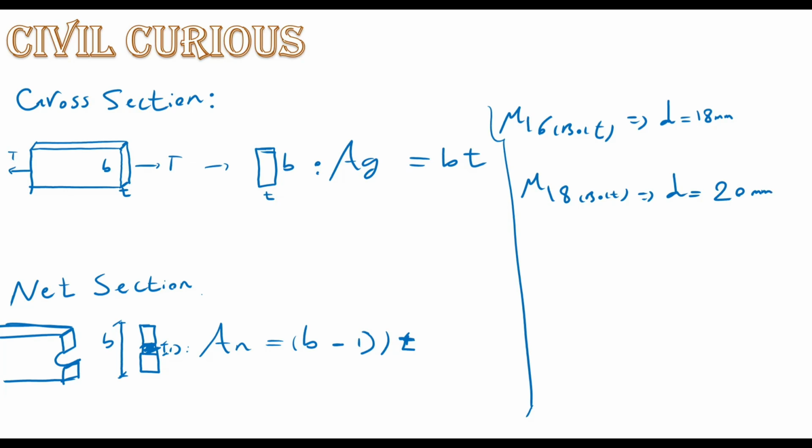Be careful that in every single circumstance, every single connection, the value for the hole should be at least 2 millimeters greater than the value of the bolt. Okay, that was another content that I wanted to address for you. Let me continue, everybody, with our topic about tensile elements.